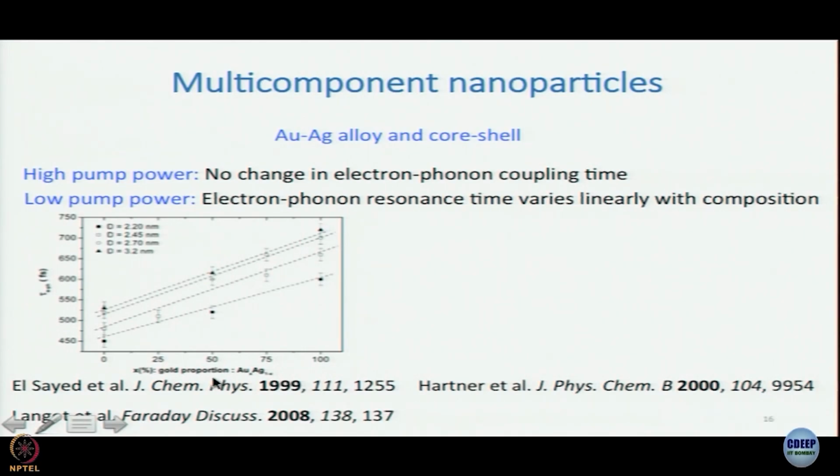The x axis is mole fraction of gold. Remember what happened for gold platinum? These plots were not linear, is not it? Remember, it fell. Here it is linear. Why is it linear? What is the difference between gold silver and gold platinum? The difference is that these rho values are the same for gold and silver, they are more alike each other. So, alpha of gold is really equal to x of gold. Go back to that equation that we showed a little while ago and plug these values in, you will see this.